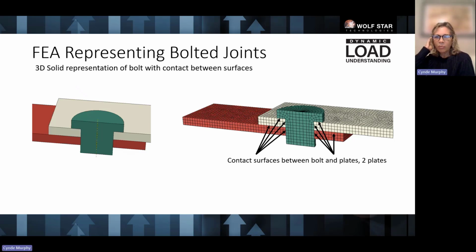So 3D solid representation of the bolt with contact is probably the most sophisticated bolt modeling technique. All or most of the parts that are in the FEM that you're trying to fasten together have to be joined as one part in your main FEM.